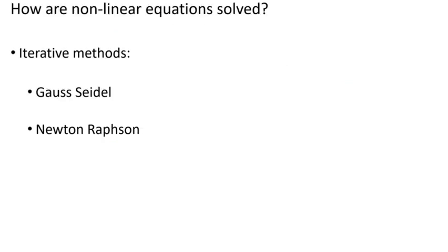So then, how do we solve this? We have to use some iterative methods. The common ones are Gauss-Seidel, and really Gauss-Seidel is kind of old. It's no longer used. Any power flow program will have some of them, not all. Some of them don't even bother programming Gauss-Seidel because it's very complicated and tedious, plus you have to maintain it. If you have that code, you have to maintain it. You have to tune it to become more stable, because if there are convergence issues, you have to tune it, and you are maintaining something that no one is using basically. So some power flow software will not even bother having Gauss-Seidel, but it's a method. But the most common one is Newton-Raphson, and Newton-Raphson has different versions that I'm going to talk about.